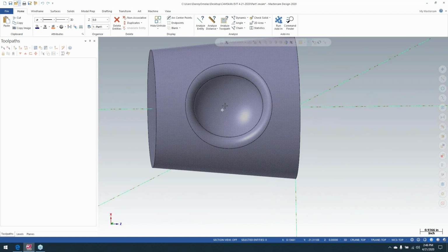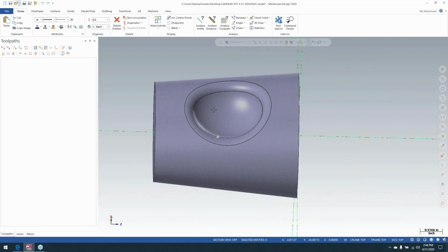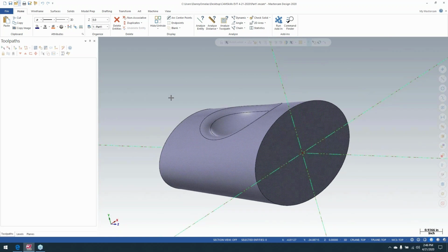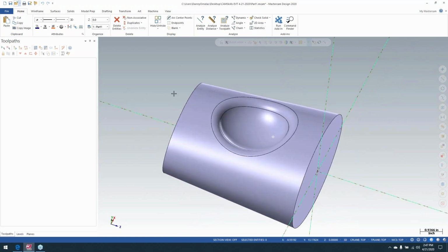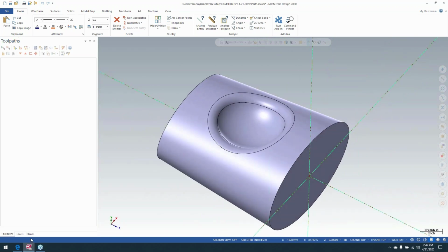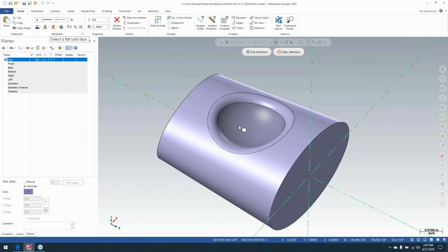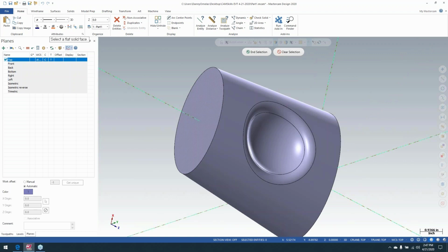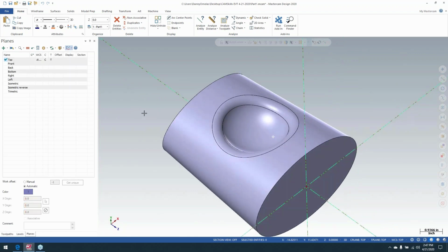You have to look at this feature normal to the Z-axis. So we look at these things like this, and say, how do we create a construction plane and set up a WCS? This is where the geometry still comes in, because if I was to come up here to the planes and go to solid face, I'm not really sure that I can pick any of these faces. I know I can pick this face and this face, but that's not what I want. I don't know what the angle of this is. So let's come back and we can create some geometry.